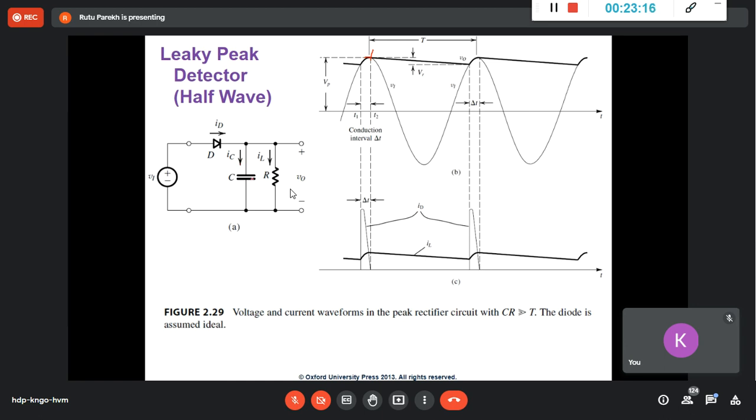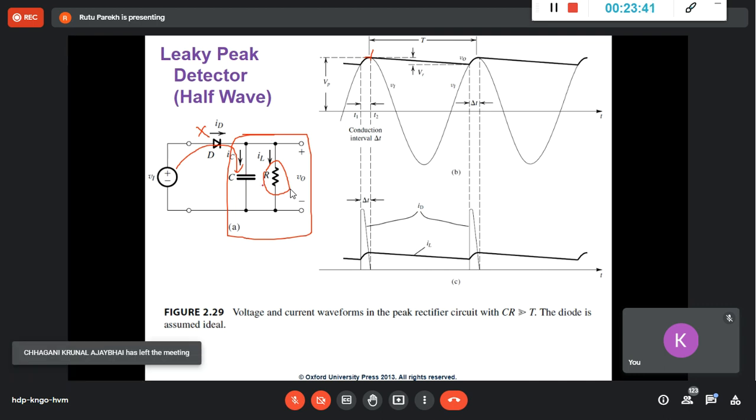Okay, so now what has happened? This capacitor is no more charging, because the charging has stopped. And then it is getting a way through this R to discharge. Now this is providing a path to discharge. And now this was reverse bias. It was cut from here, and the only resultant circuit is this. And this, which was charged fully, will start to discharge from here.